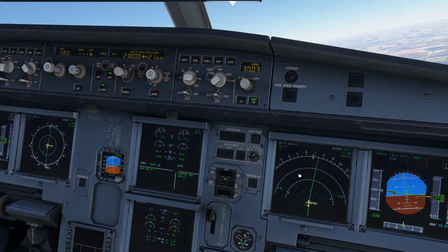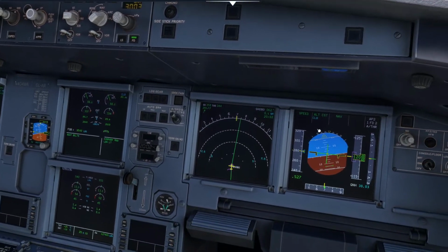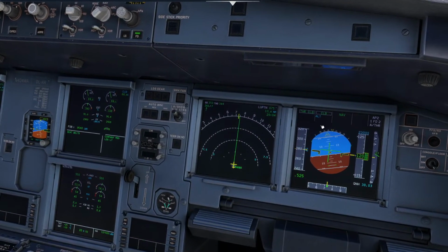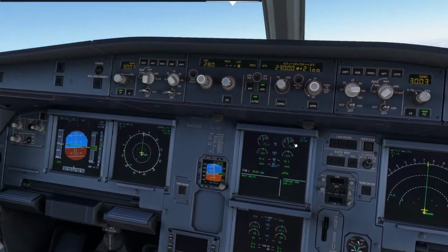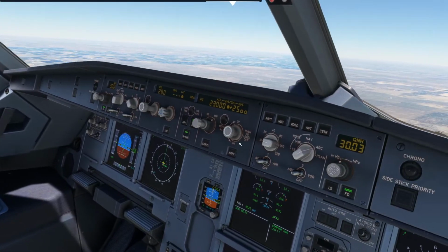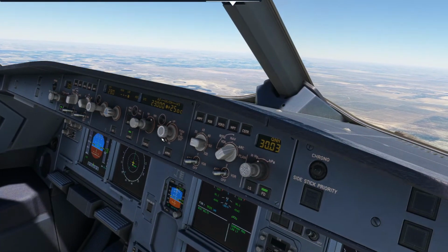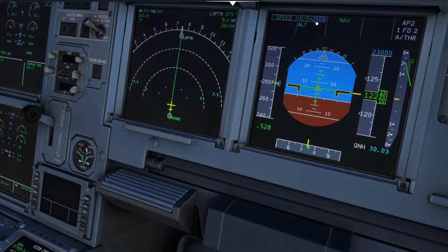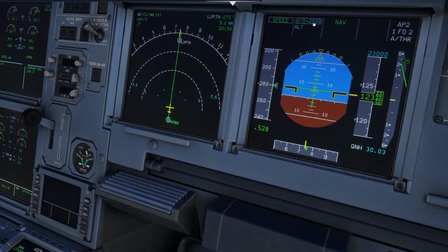So watch how it turns, and watch how it says altitude constraint. Oh, you see how it says climb now? It's going to climb again, right? So now it's going to climb, but I could override it and put 2,500 feet a minute and pull the button out to do a vertical speed climb. So watch, 2,500. Now it says vertical speed 2,500.